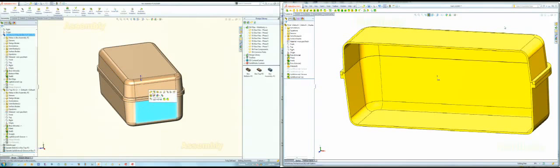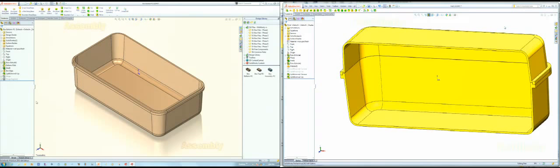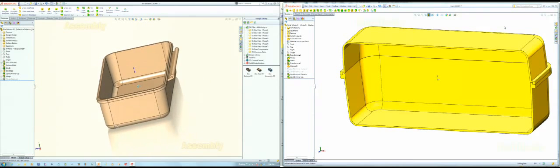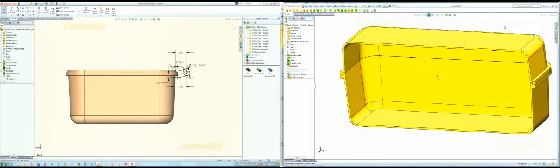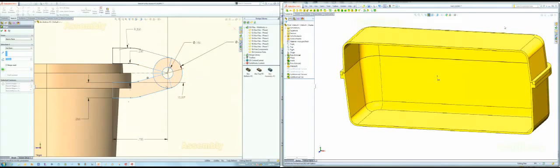Okay, so I can just open the bottom box by itself because I really don't have anything to do in context here. Let me just unsuppress the first component. There's the long extrusion. It was made from this sketch. And if we go to the right-hand view, if we look at the way the extrusion was created, if those of you know how to select contours, we just used part of the sketch and basically took this and this, extruded it. When I go to the top, I'll use this section up here plus the circle. And we know everything's going to line up.